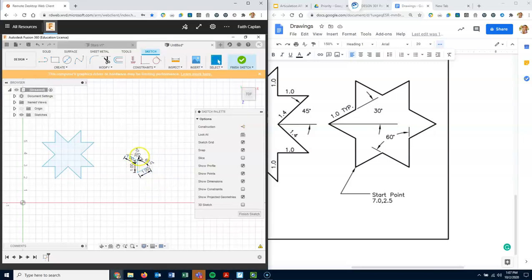All right. Okay, so now I'm going to click my line tool again and keep going. I have to get right on the point where I had this. And then it's 1, tab, 30. And push enter just so we can see it. There, looking good. The next one's going to go straight up again.